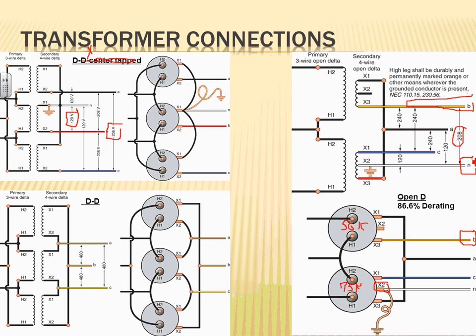Yeah. Right. But you need at least two hots on the primary side, no? We had two primary hots, and we needed three phases. Okay, then the third, you got through the ground. Yes. So that will be your phase. So if you have phase A on the utility side and phase B are the only two phases coming to your area, then what you do is you take this one to the ground on this side, right? Is that what you guys did?